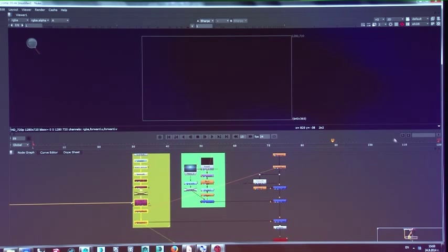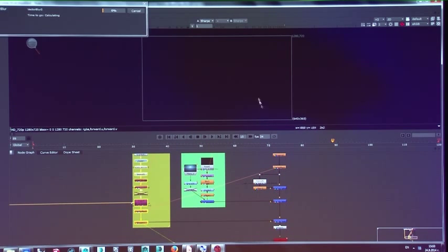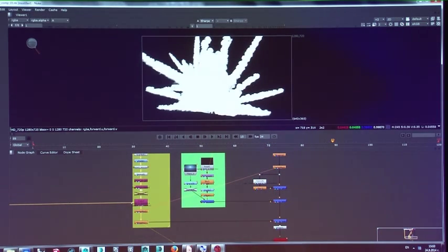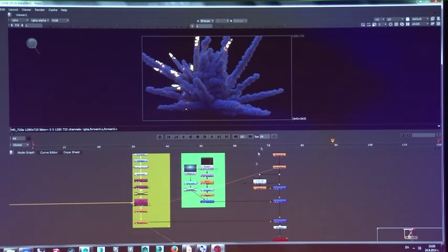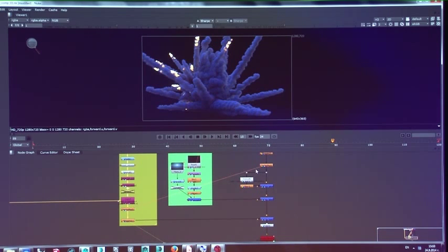And here I have the explosion, which is not there yet. So here's the explosion. I have color corrected that. I'm applying a velocity-based motion blur in post, which is much cheaper to calculate. But again, you have to make considerations before relying on this solution, because if you have objects that are moving and passing one in front of the other, this solution might not always work fine.